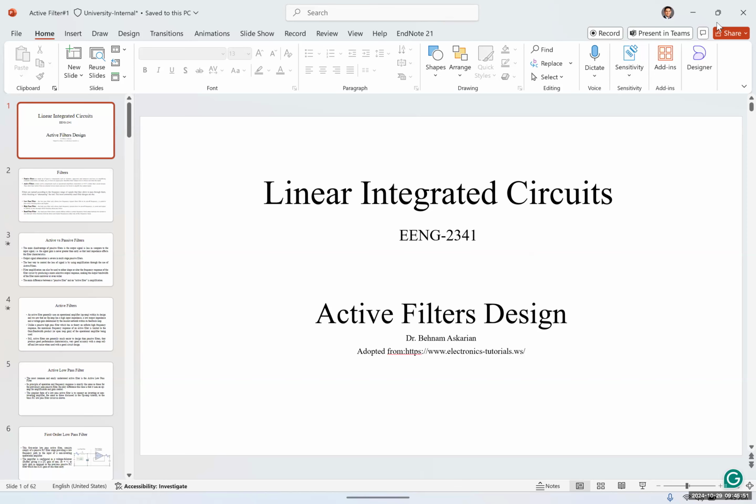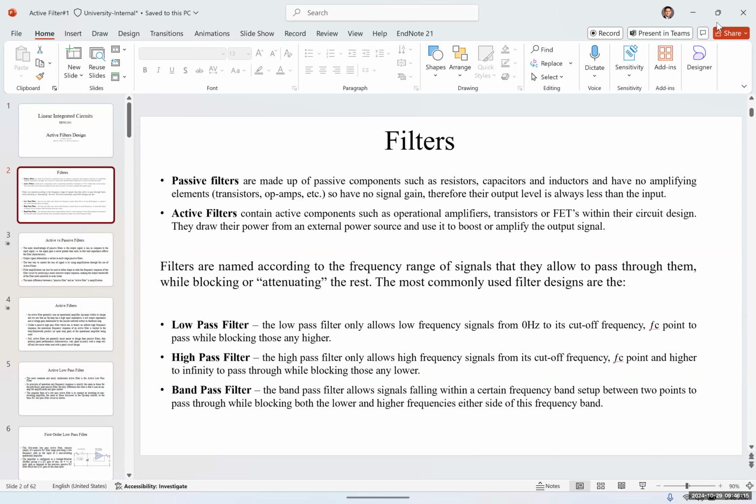Now, how can we use that to our advantage? You may think the upper and lower cutoff frequency is a disadvantage or con of an op amp, but actually we use those characteristics most of the time to our advantage, as a pro, to create a filter, which we call a low pass filter or high pass filter.